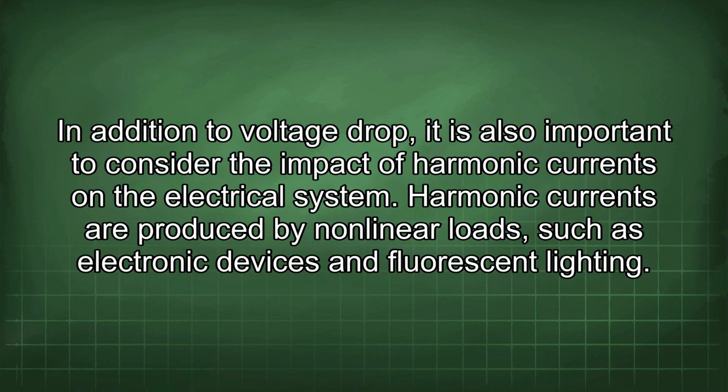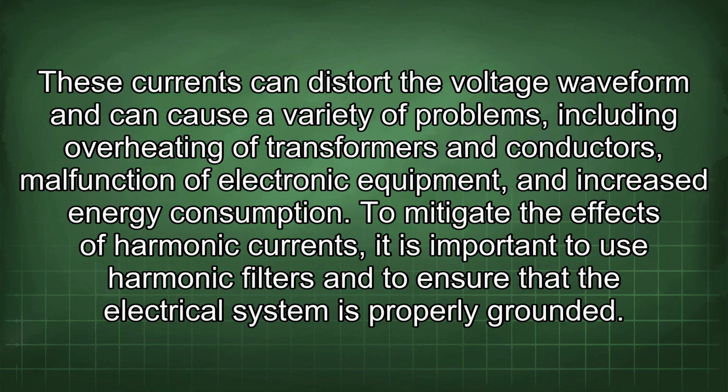In addition to voltage drop, it is also important to consider the impact of harmonic currents on the electrical system. Harmonic currents are produced by nonlinear loads, such as electronic devices and fluorescent lighting. These currents can distort the voltage waveform and can cause a variety of problems, including overheating of transformers and conductors, malfunction of electronic equipment, and increased energy consumption.